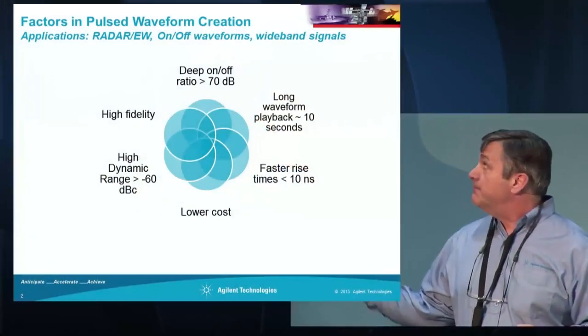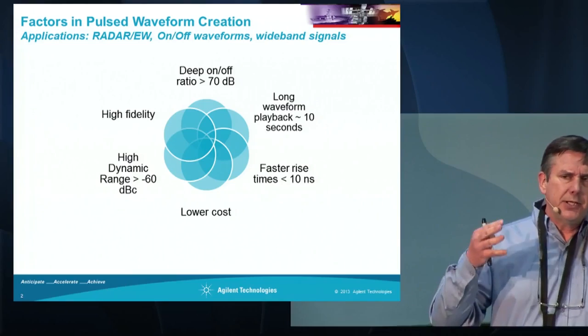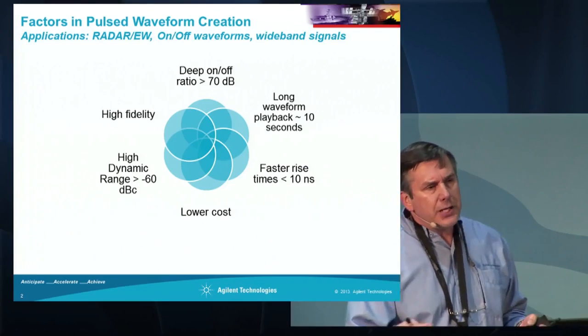So a long playback is critical, and you might say, well, I just need a deep memory source. I'm just going to stuff bits over a bus to my signal generator, and I can have hours of data because I can have terabytes of RAID array or some other huge solid-state memory resource. The key there, though, is getting that data across that bus.